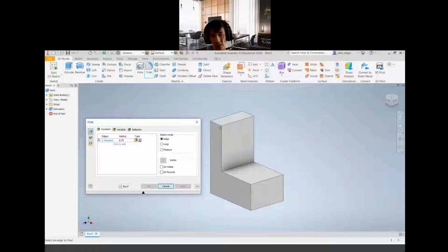Okay, so I would like to click on these edges. You see, one edge has already turned into the fillet. Once selected, you can continue making selections, click another one. You will see it turn into the fillet itself. No need for you to actually create an arc when you create your sketch. Then continue again since you have the same radius for this bottom part also. You see 3 selected, and we should end the process here with another fillet. So in total, you have 4 edges selected with the radius of 0.75.